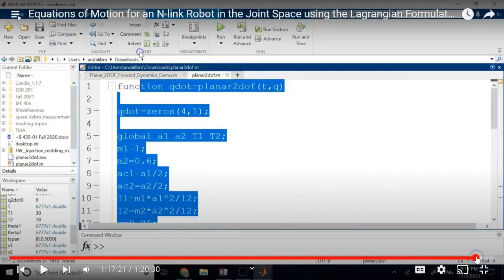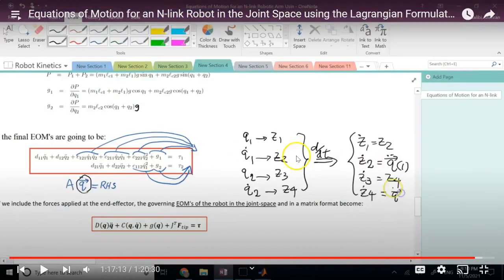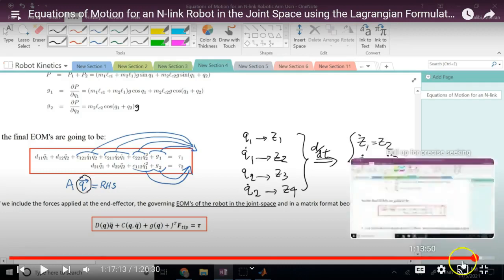There we go. You see here? Going from these equations that you derive symbolically to these ones that ODE45 is using, we did that manually. We wrote that ODE function for these 4 equations manually. Now my question is, could you do it automatically? And the answer is yes.